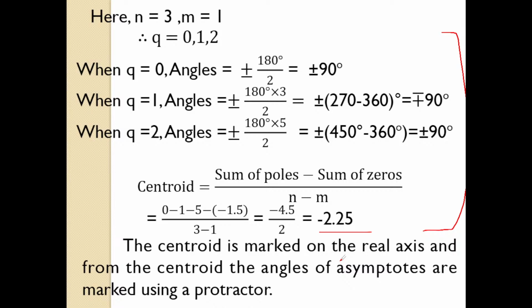Take the denominator, equate it to 0. That is our characteristic equation for the closed loop system. Just rearrange the terms to get an expression for K. So what is K?